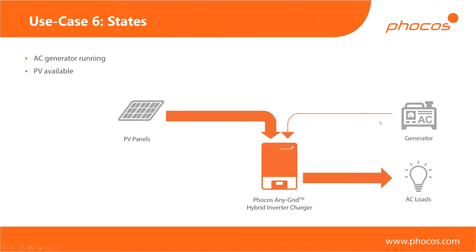And that's the reason we also need that firmware, is because we're extremely fast now to make sure that if you suddenly turn off this load, that we're not backfeeding any significant power to the generator, which could damage it. To be clear, within 50 milliseconds, we've reduced that backflow to 0, which is well beyond anything typical grid-connected can do.